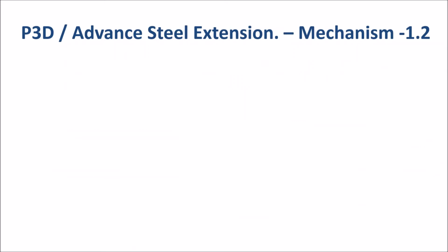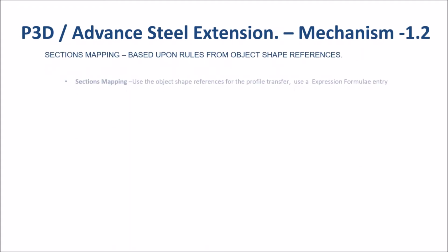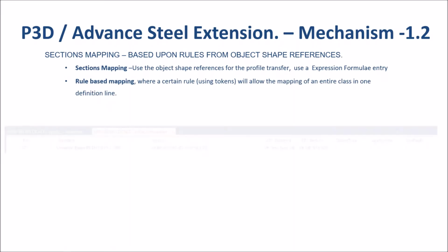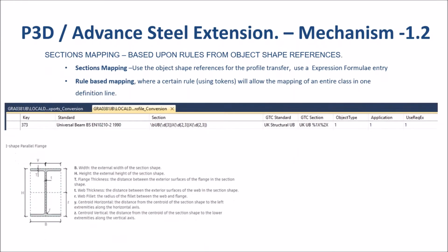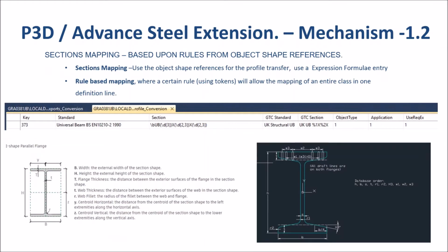A lot of the data behind the SMLX is actually based upon the Revit interface. It's quite big in that, and there's been a lot of improvements. Basically, inside the plant platform, they're using a cut-down version of that. It literally is one-directional. The one inside Revit is bi-directional. So this is a one-directional one, and what it does is it looks at the shape itself inside Plant 3D, and obviously you'll have common references for the height of the section, the thickness of the flange, the web, even the root radiuses, and things like that get then transferred across.